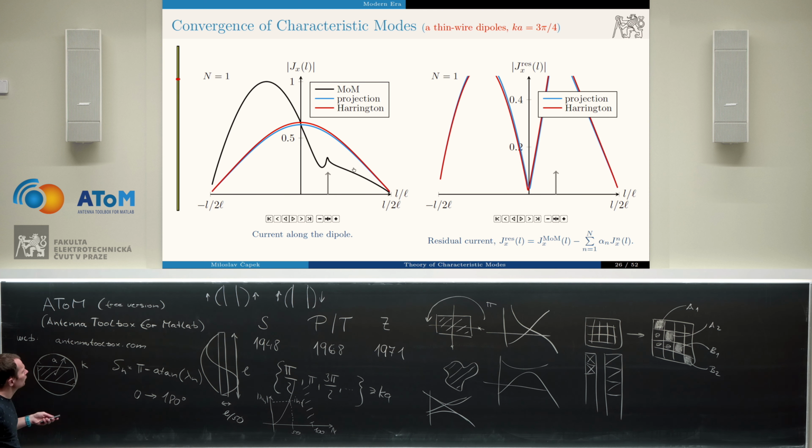And Harrington actually published that we can get this information directly from the behavior of the eigennumber, because he wrote in this paper that this relation is approximately equal to the Q factor. Here, and with all the details in this paper, we are showing that it's not only an approximation, but it's exactly valid if you sit at the self-resonance of your mode.